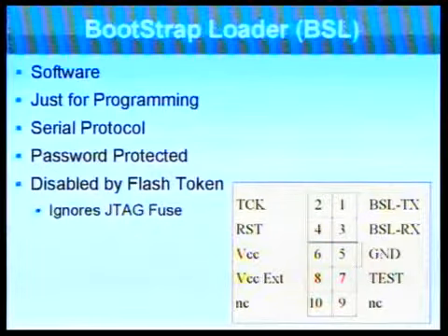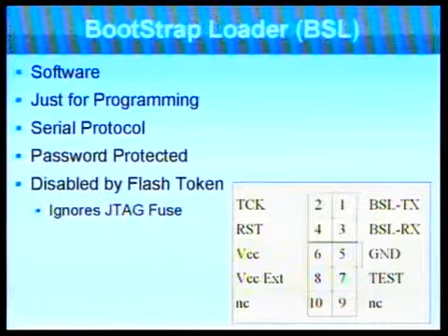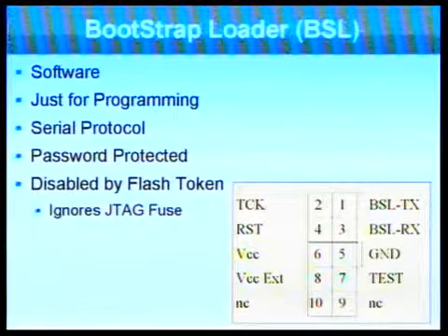It's only intended for programming, not for debugging. The closest it has to debugging features is the ability to jump to a pointer or to read from memory. You can't single step, but at the same time, it has a password protection mechanism that's independent of the JTAG fuse protection. So if you blow the JTAG fuse, you can still access the chip through its serial port.